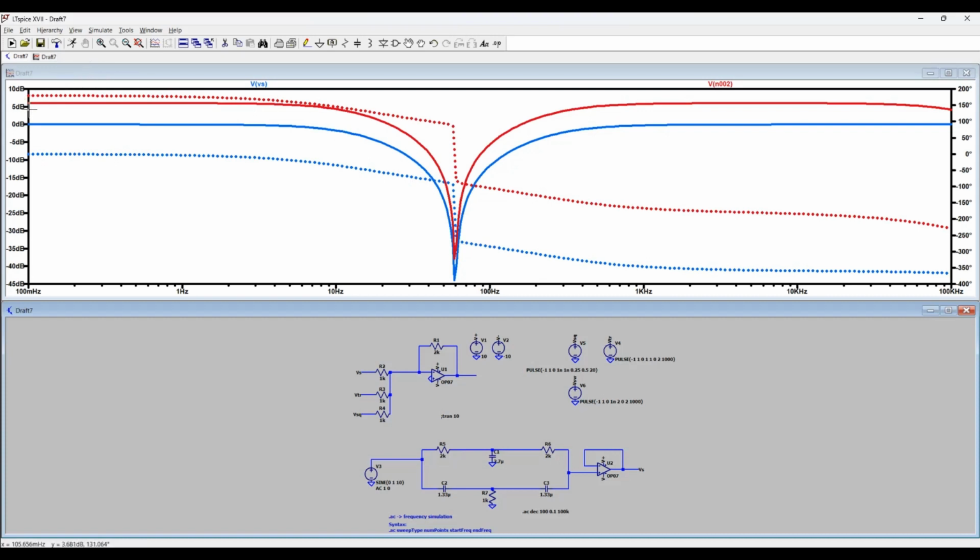And so here we can see that we actually have a gain that's slightly above 5 decibels, and that's because our summing amplifier has a gain of 2. And if you take 20 times the log of 2, you actually get 6 decibels. So if you convert your gain into decibels, you get 6 decibels, which is why we have a 6 decibel gain over here. But as you can see, our notch filter is still working properly at about 59, 60 hertz. And so we can kind of confirm that this filter is working to our expectations.